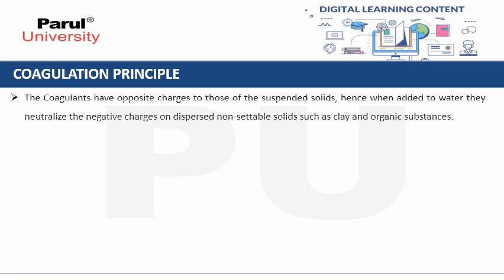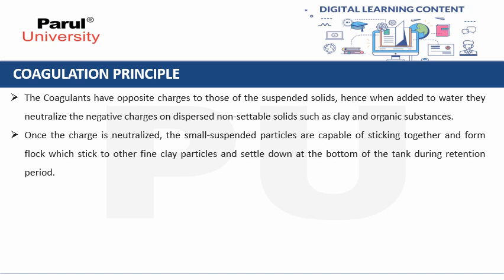Coagulation principle. The coagulants have opposite charges to those of the suspended solids. Hence, when added to water, they neutralize the negative charges on dispersed non-settleable solids such as clay and organic substances. Once the charge is neutralized, the small suspended particles are capable of sticking together and form floc, which sticks to other fine clay particles and settles down at the bottom of the tank during the retention period.